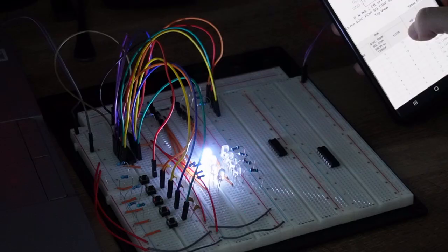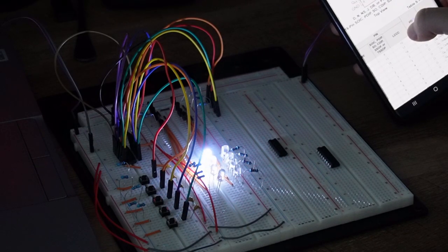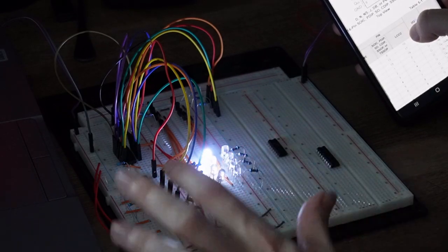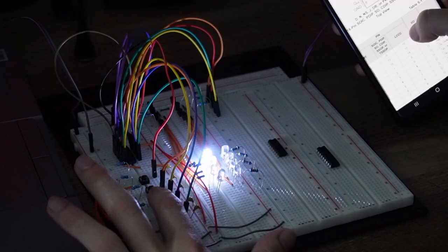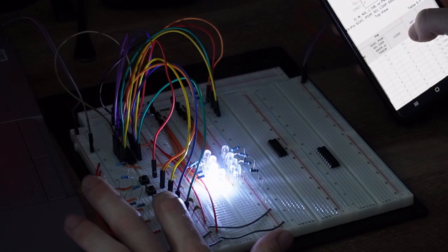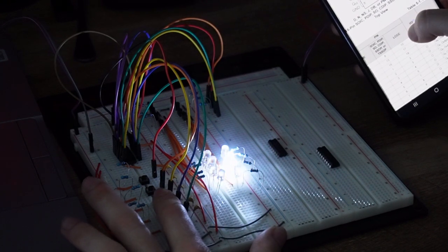And because the serial register is tied high, I can just toggle the clock signal to shift in basically nothing, but it will shift the whole value of the shift register. So we'll see the LED will move by 1. So if I just keep shifting and then sending it to the output, we'll just see this LED goes through the whole system.